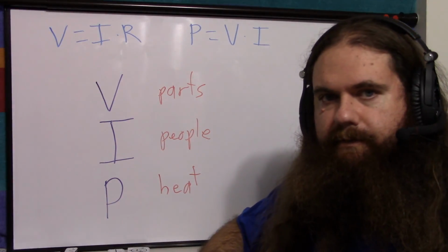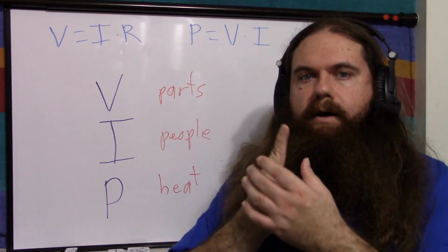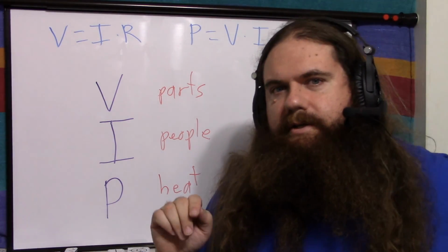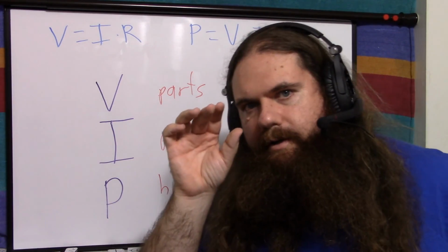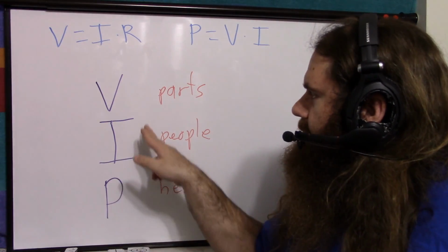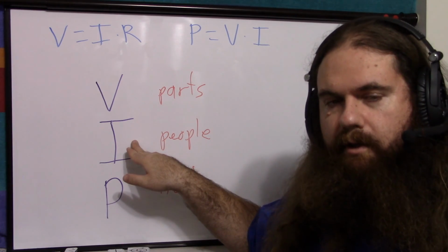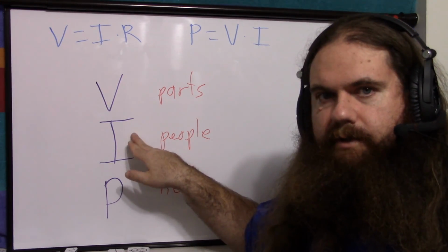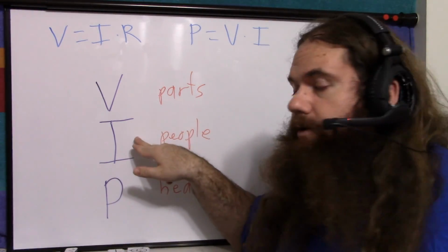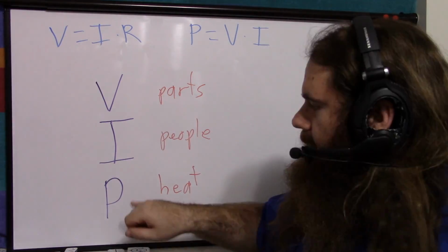So this was just a quick review of basically the super safe, ultra conservative baseline, a passive scan that resists whatever is being done to it. Basically, you just peek in the door. You just take a look through the peephole. And then you can get further and further and further. You can start applying a very small voltage and turn it up. You can start applying lower resistance to try and get whatever current the thing is generating to increase. Or if it's not generating current, you can start generating current yourself slowly. But we start from zero and the power follows.